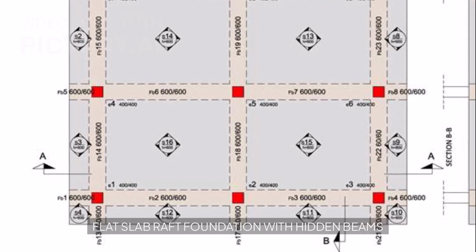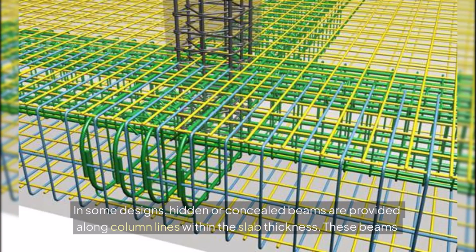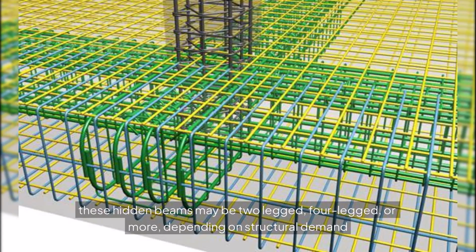Flat slab raft foundation with hidden beams. In some designs, hidden or concealed beams are provided along column lines within the slab thickness. These beams act as stiffeners, reduce slab deflection, and help control punching shear at column locations. The stirrups inside these hidden beams may be two-legged, 4-legged, or more, depending on structural demand.